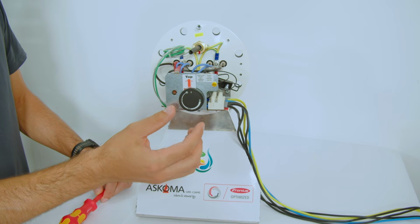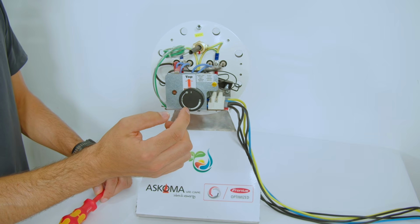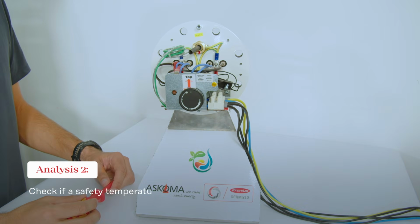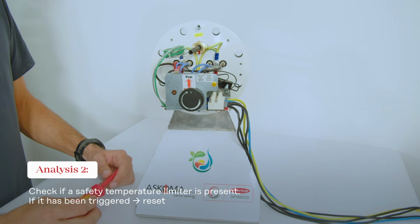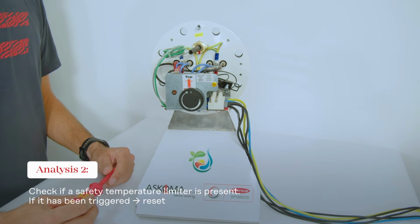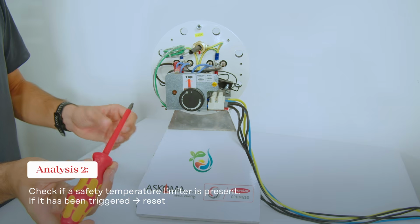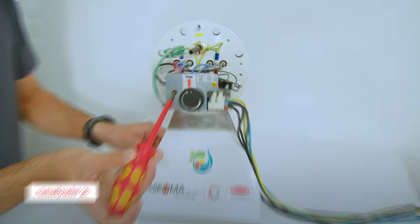Important for all your further investigation, leave the bimetal switch off, so in the minimum position. Secondly, some heating elements have integrated a security temperature limiter. And this temperature limiter can be activated, for example, when temperature fluctuations happen. In order to deactivate this security limiter, in this case, we need to press this button here.